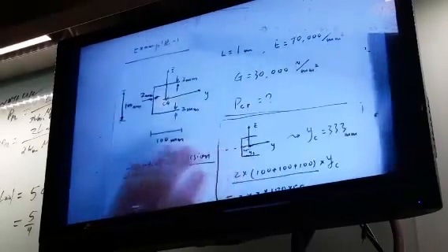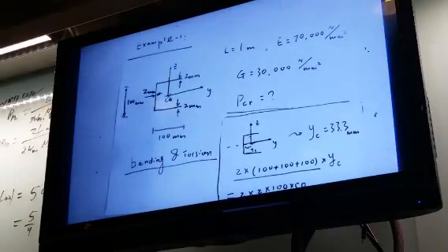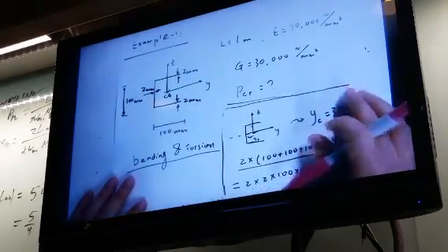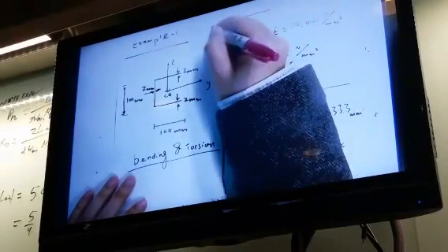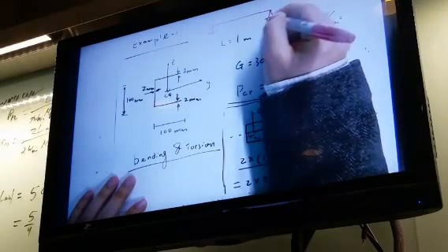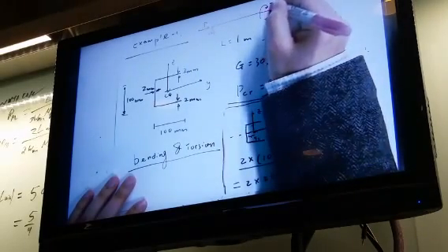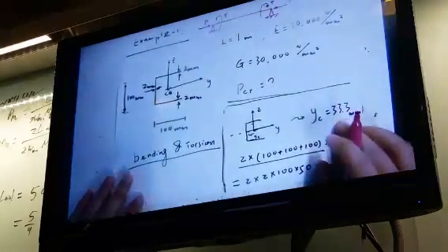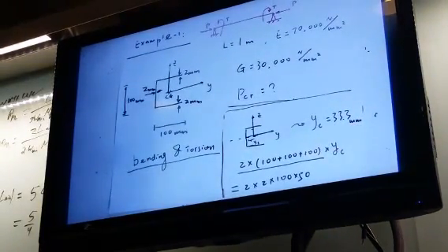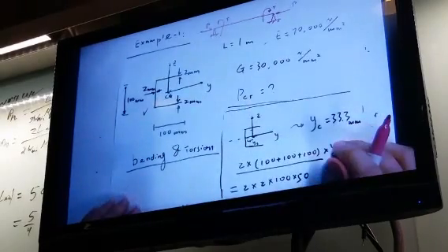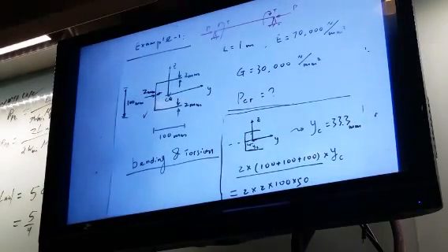And the second thing we learned is when you have simultaneous buckling and torsion. This is the beam. And you not only have compressed loading, you also have torque loading applied on the column structure. And this is a typical cross-section of the beam. So in this setup, this is just an example. In this setup, the beam can be buckled in the XY plane and in the XZ plane, and also a torsion plane. So three possible buckling modes.